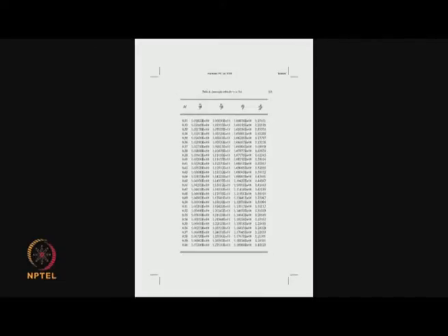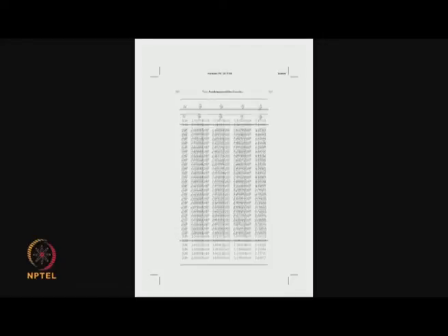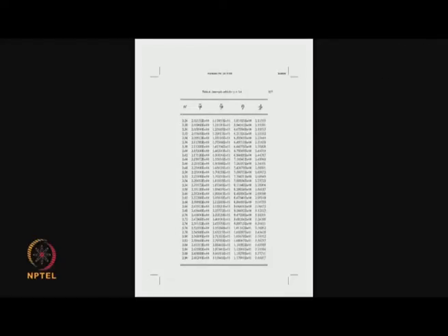You can see from here, isentropic table, and we said that A over A star is given to be 3.5, and we wanted a supersonic solution. So, you can see that A over A star 3.5 comes somewhere here, and this was the supersonic Mach number that we picked up earlier: 2.8 and A over A star 3.5.